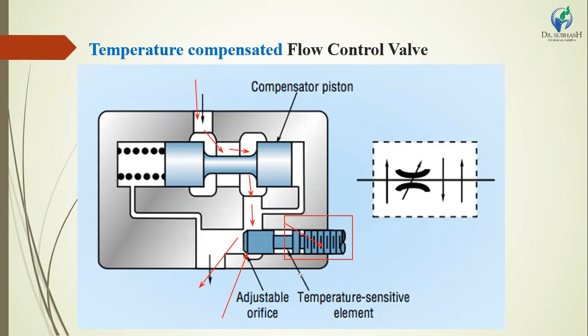If the temperature rises in the hydraulic fluid, this spool moves in the closing direction and closes the area of the orifice. This orifice is closed.